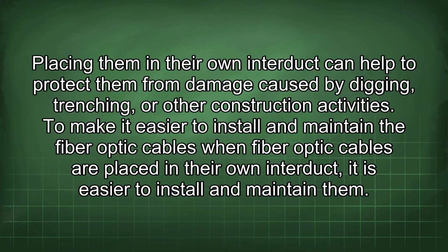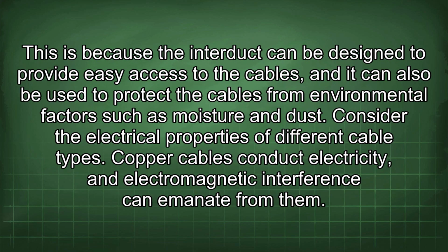To make it easier to install and maintain the fiber optic cables: when fiber optic cables are placed in their own interduct, it is easier to install and maintain them. This is because the interduct can be designed to provide easy access to the cables, and it can also be used to protect the cables from environmental factors such as moisture and dust.